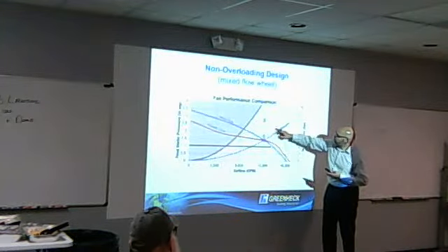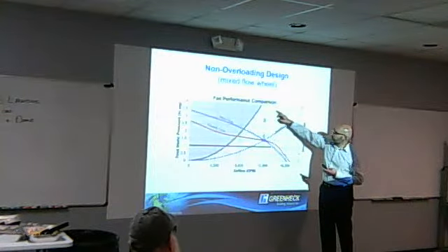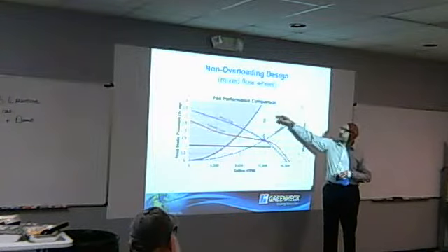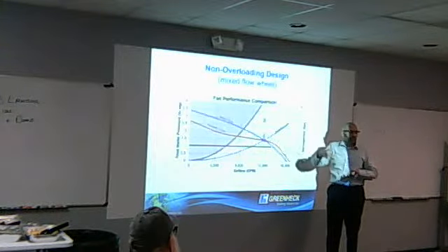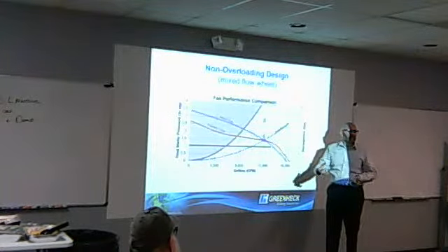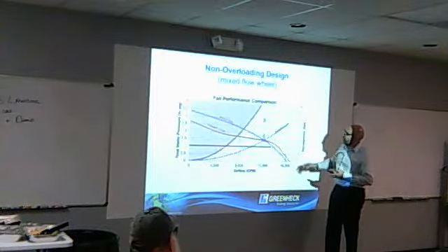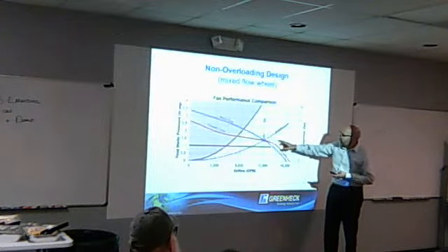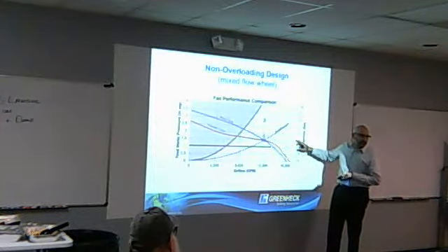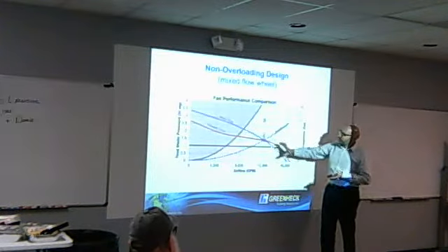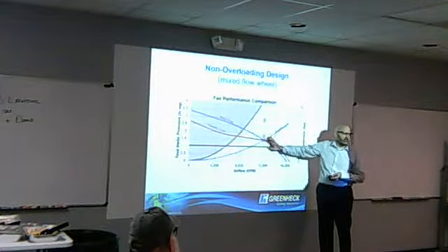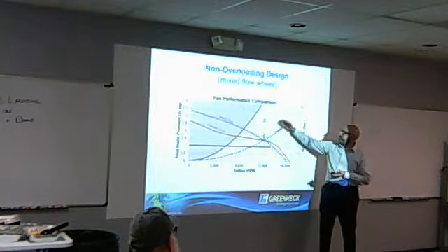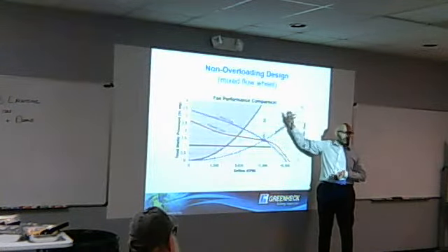What happens to the brake horsepower on the forward curve wheel? It goes up, even higher. You get to a condition where you could overload the motor that you have, depending on the horsepower you select. You got it, exactly. But what happens to the mixed flow point? It actually comes down slightly. So normally when you're selecting these mixed flow wheels, you're near their peak efficiency, peak brake horsepower. And if that condition happens, you're still safe, but if it happens on a forward curve wheel, that could be overloaded.